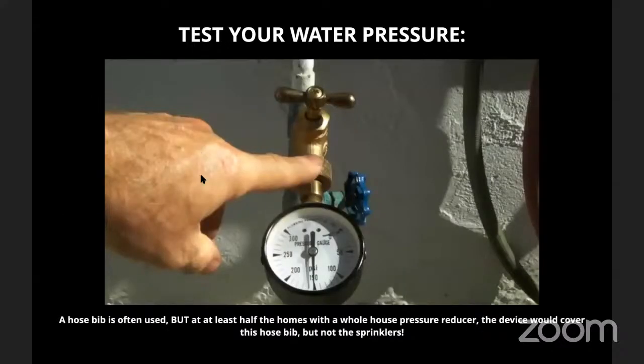And this is actually my house. When I first moved in a couple of years ago, there was no pressure reduction, and I'm in the city of Pomona. Water pressure is really high. You can see here, just at the hose bib coming off the back of the house, 150 PSI. That's crazy high. That is so high that it can cause problems for the actual sprinkler valves as well. So I needed to install a second whole house style brass pressure reducer just for my irrigation system.